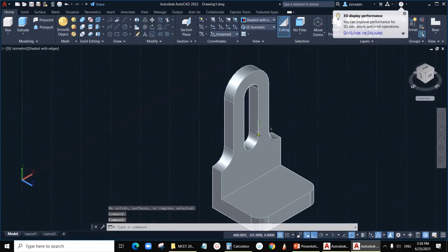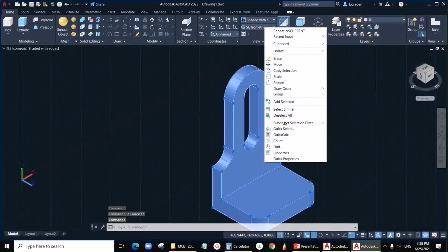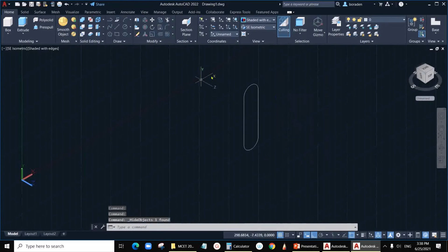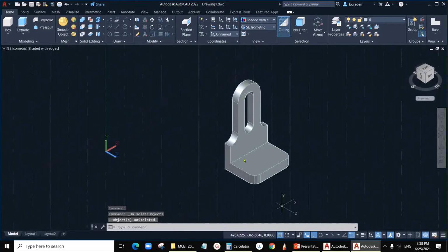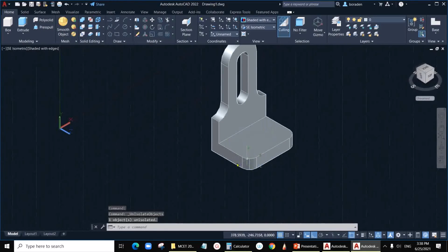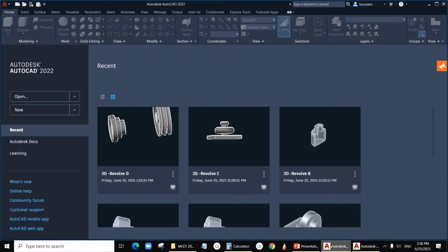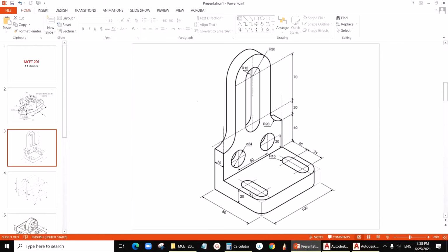What I was selecting first was these construction lines, or the lines. Okay, so I can do the same thing now: isolate, hide the object, and then this is what was being selected. I will delete it, then end isolation. Okay, fine. Now to the base, we need these 2 holes here in the base.